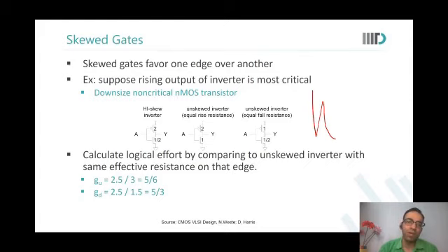So what happens now? The total load of A has reduced. Are you able to see this? Total load of A has reduced. Instead of 3, that is 2 of PMOS and 1 of NMOS, I now have 2.5 total load. Additionally, because this load has reduced, A will now transition faster, and therefore my output will also transition faster. I've also skewed, so NMOS will now have lesser on current, and I will be able to take Y to one level much faster.